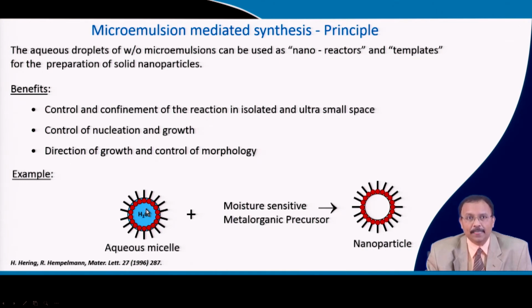So, this water is there, and you know that the surfactant which is hydrophilic, that head is here, and hydrophobic, the tail is in the other side in the oil part. So, inside this water, if you can somehow mix the metalloorganic precursor, the alkoxide. I already talked about the Sol-Gel synthesis. So, if this kind of alkoxide, the reaction you can initiate inside this water, they will hydrolyze. So, your condensation product will have a very, very uniform kind of particle size.